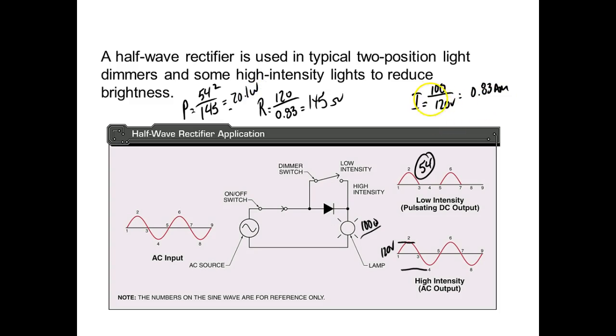So look, we halved the voltage, so we went from 100 watts down to 20 watts. Some people take for granted that if I half the voltage, I can put that on a test, in any class. And they'll say, if I half the voltage, what happens to the power? And more than one is going to say the power will halve. The power varies with the square of the voltage. So if it goes up, it's the square. If it goes down, because the problem is that when we drop the voltage, what happens to the current? It goes down to the load, right?